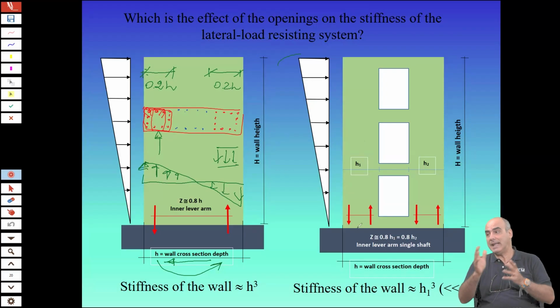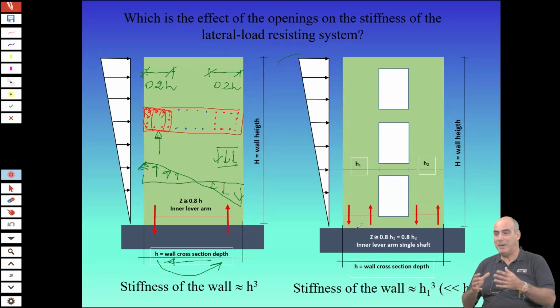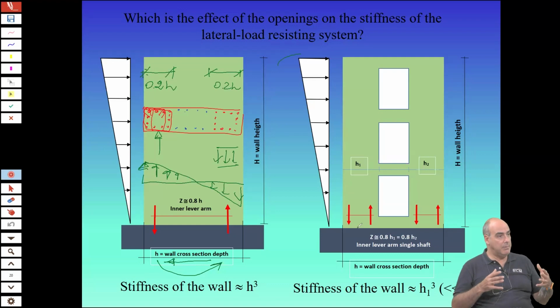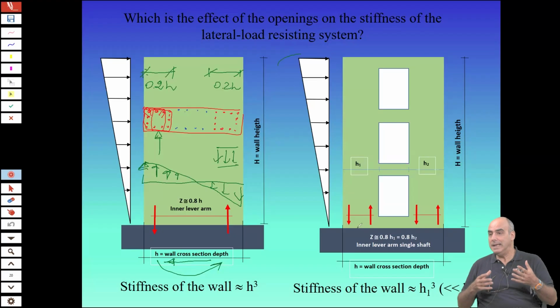And you have to resist half of the force at least if you want to split it. So you also have a penalty because you have to resist a force which is half, but you have a lever arm which is 35%. So you have a magnification factor of about 1.6, 1.7. So it's a problem of needing to design with reduced capacity. But there is another issue.